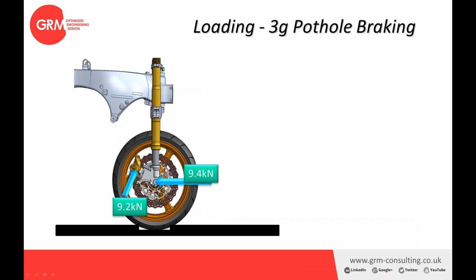So in terms of how this has been developed and optimized, we've taken the worst case loading, quite an abuse load case of the motorbike being braked hard with the back wheel off the ground, and then the front wheel dropping into a pothole, inducing a 3G pothole braking load case. So here we've got loads applied to the wheel axle and obviously the braking torque applied via the brake caliper.